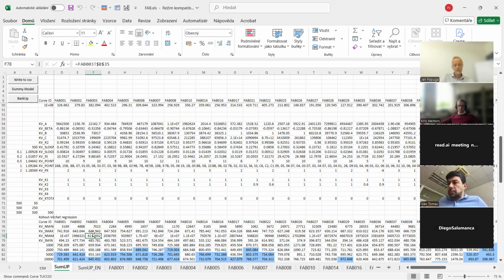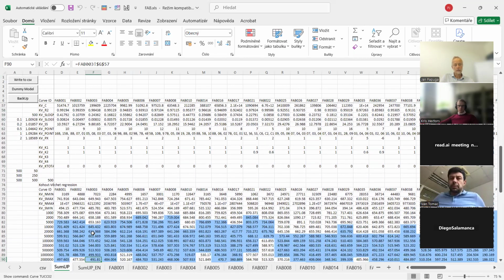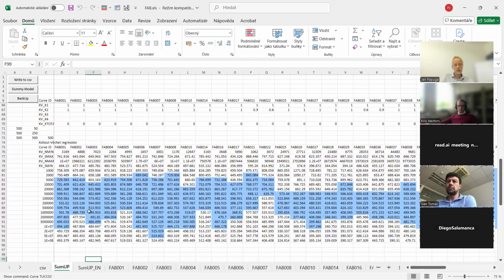Plus I see in which lifetimes my model of the fatigue curve is interpolating and in which lifetimes it is extrapolating. Blue background color means that this is the interpolated area. So I can check in which lifetimes I am interpolating for any future task.